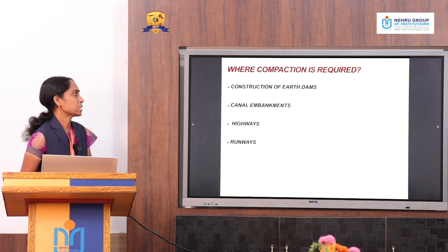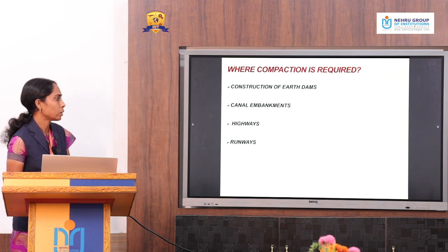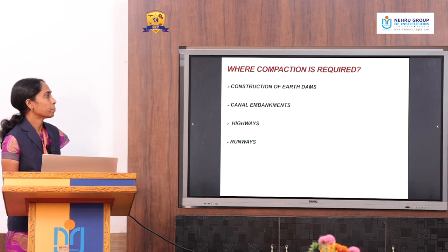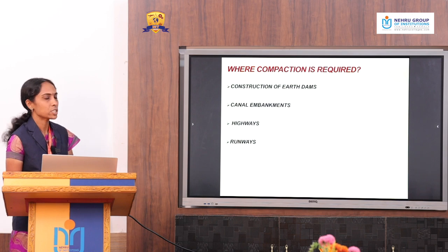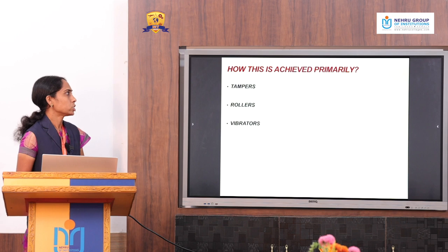And where is compaction required? Mainly it is required in the construction of earth dams, canal embankments, highways and runways. Prior to this construction the soil has to be prepared, that is, the compaction has to be completely done. And how is this achieved primarily?